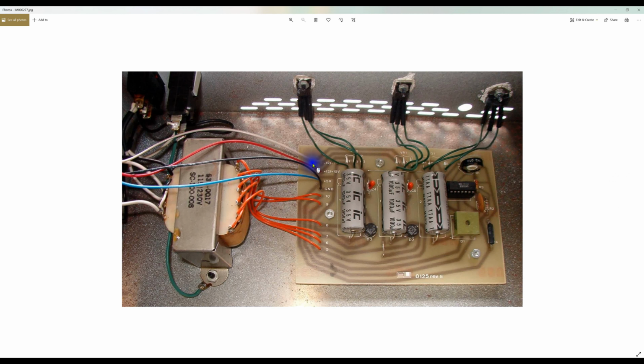There's 3 different taps coming in off the transformer. AC tap in, full wave bridge rectifier, capacitor for smoothing, and then a voltage regulator. And same thing here, and then a larger diode bridge, just because the plus 5 is going to have much more current load on it. And an adjustment, pretty typical for the era voltage regulator.